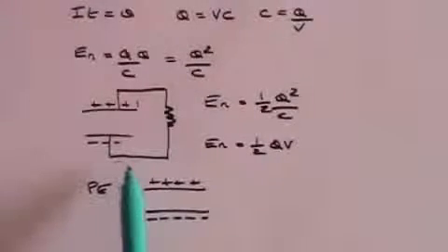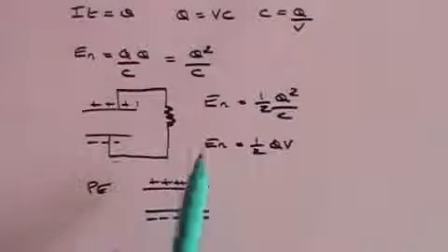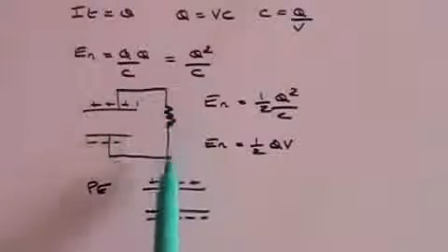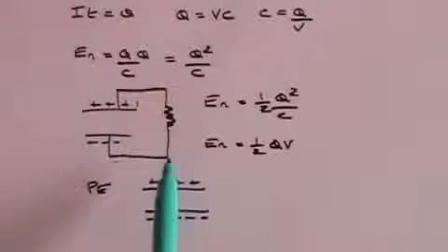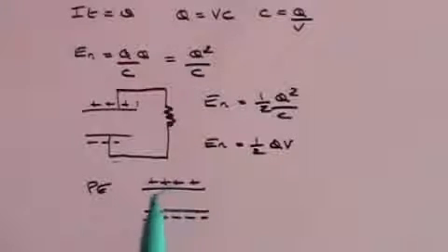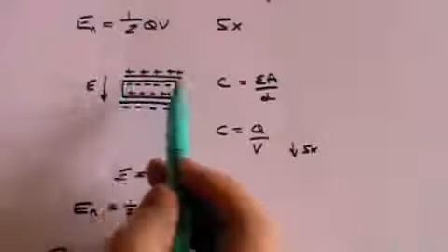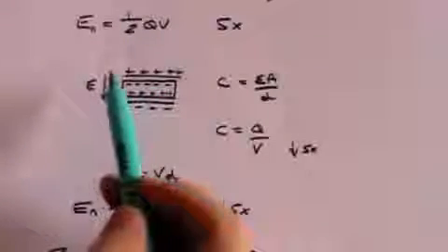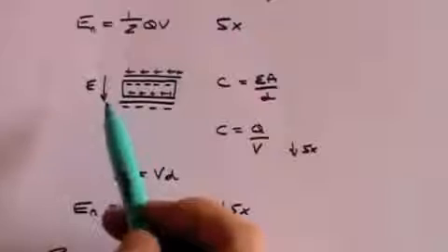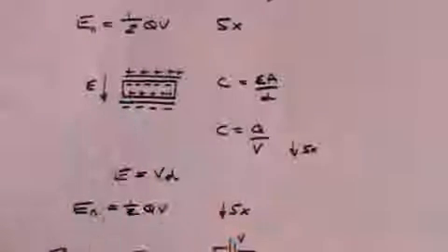How is the energy stored in the capacitor? Well, I try to explain that here. It is stored as potential energy such that it can be released if you connect the capacitor to some sort of circuit. That energy will flow as a current through a resistor and discharge in that way. Is the dielectric affected? Yes, it is. The dielectric has an induced charge on it, and it's that induced charge that creates a field within the dielectric that opposes the field between the plates, and that's what changes the capacitance.